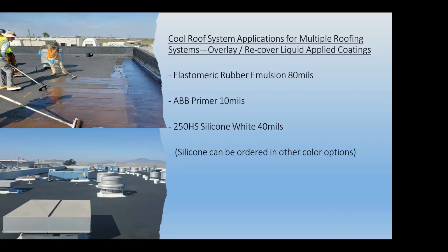So when you're looking at your roof, you do your inspections, you have leaks throughout the years that you've tracked. If you have 2-3% of your roof that has a leak, why would you remove 100% of your roof? It doesn't make any sense. You can fix what you have in place, you can restore it, put a brand new system on it, a brand new membrane, and extend that roof life cycle out with warranted back products.